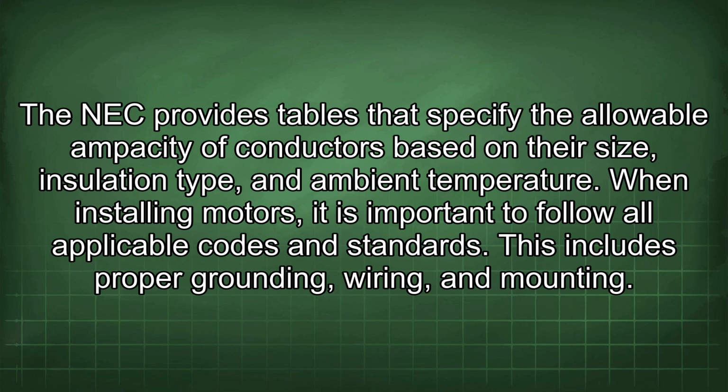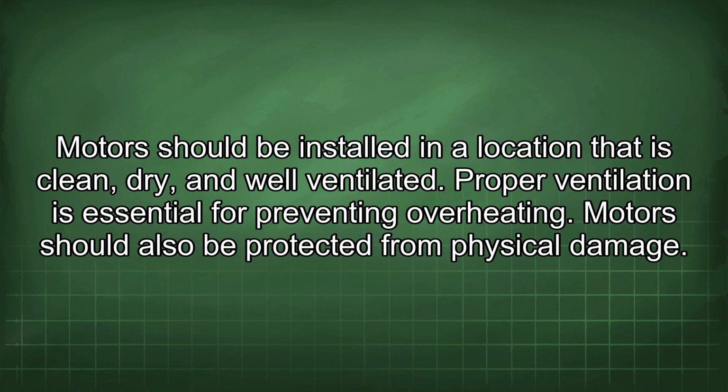When installing motors, it is important to follow all applicable codes and standards. This includes proper grounding, wiring, and mounting. Motors should be installed in a location that is clean, dry, and well ventilated. Proper ventilation is essential for preventing overheating. Motors should also be protected from physical damage.